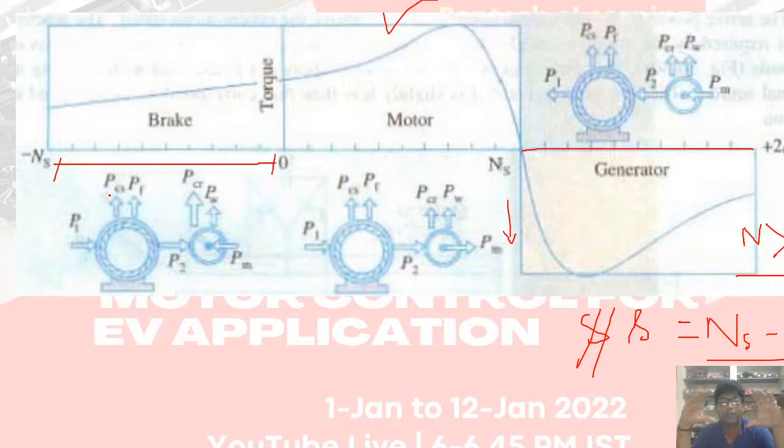Say the locomotive wheel is rotating at 1000 rpm. First the mechanical brake will not be applied, first the electrical brake will be applied, then slowly it will come down, and then your mechanical brake will be applied to stop the locomotive. This is done everywhere, for EOT cranes and everywhere.